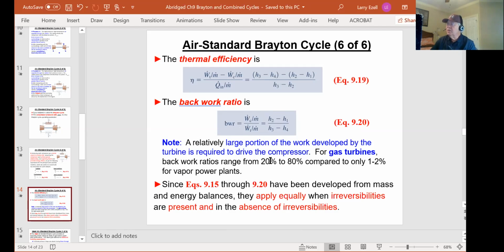We usually don't do it. We don't have it that way. We want to define how well our turbine is performing relative to the best possible performance. The best possible performance, as you probably know, is the isentropic, reversible adiabatic work process. So we put that process in place and calculate it, and then compare that to our actual process, and we get a real good idea of how we're doing efficiency-wise.